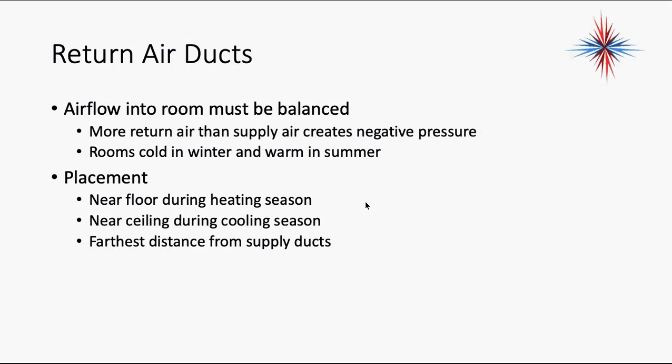Airflow in a room has to be balanced. If I have more return air than supply air, it creates a negative pressure in the room. Okay, by negative pressure, I mean that the air pressure in the room is lower than the air pressure in the other rooms of the house or the outside environment.